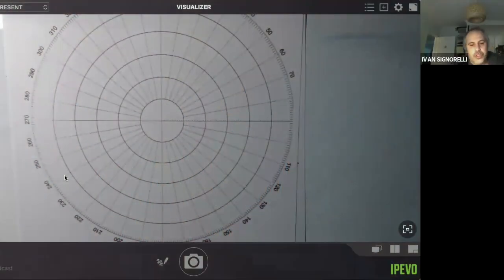Assume that it's nighttime with visibility of about 2 miles. Your radar is operating on the 6-mile scale in course-up mode, which is similar to head-up mode. For each of the following plotting sheets, firstly, assess whether there's a risk of collision. Whether you cross ahead of the contact or astern of it. What's the target CPA, or closest point of approach? And which light will you see when the vessel first appears: port, starboard, or overtaking? Remember, you've got about 2 miles of visibility. And what's the target's course and speed? So we want to answer all those questions for each one of these problems here.